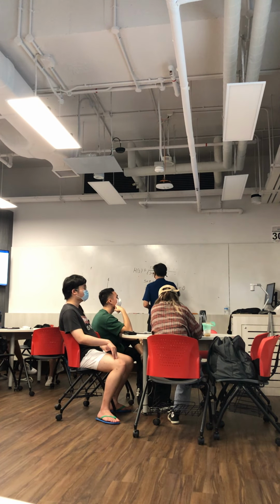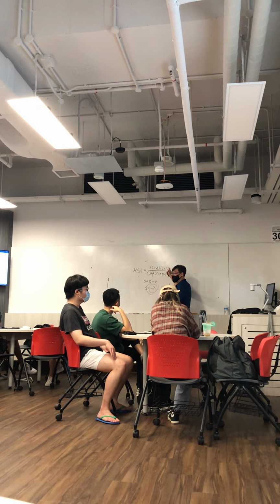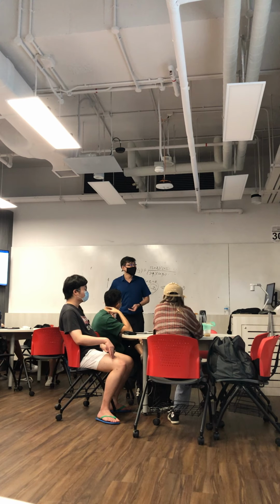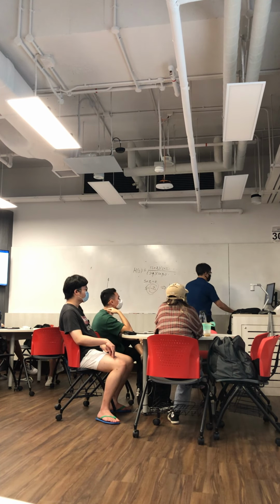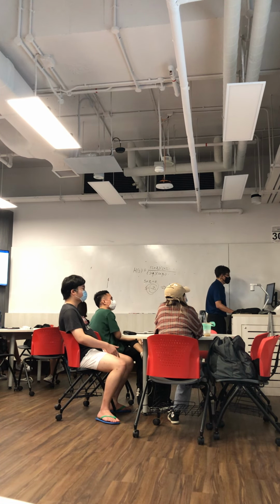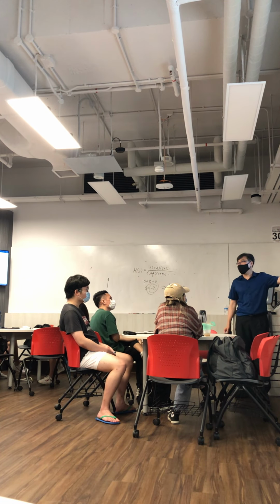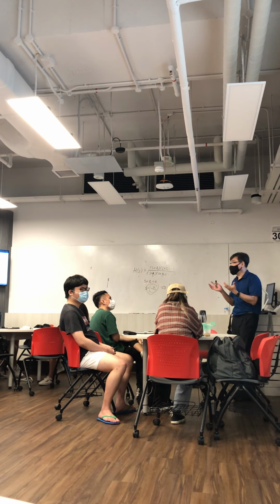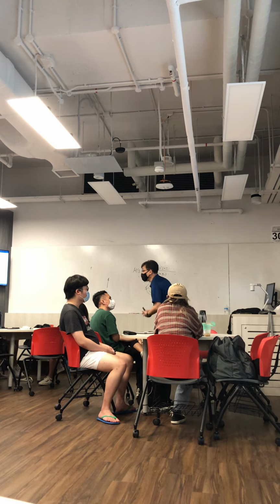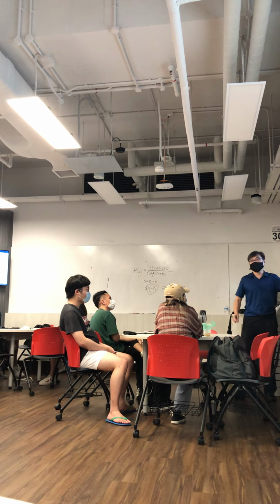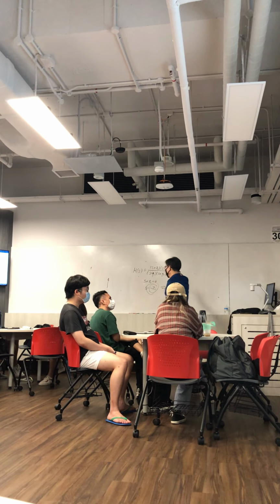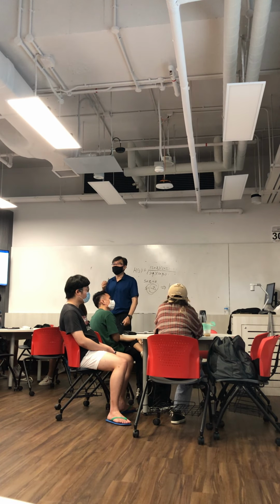Can you determine the other zero? S equal to minus Z2 is also a zero. This is a point, it can be a complex number. Then we change it to phase and magnitude. When your S is equal to this, the magnitude of the transfer function becomes 0. That's why it is called a zero.